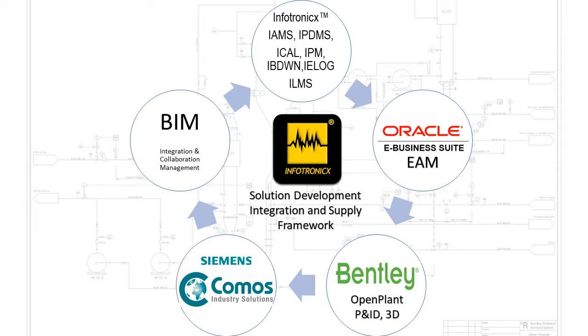P&IDs are usually created under the supervision of a process engineer who is responsible for process flow, equipment identification and sizing, flow rates, control and related information. As a project progresses, it becomes necessary to tabulate, manipulate, sort, and/or organize nearly all information that might be present on a P&ID. Information pertaining to items such as motors, instruments, valves, piping, and interlocks is arranged into lists or reports for reasons ranging from purchasing to process control.